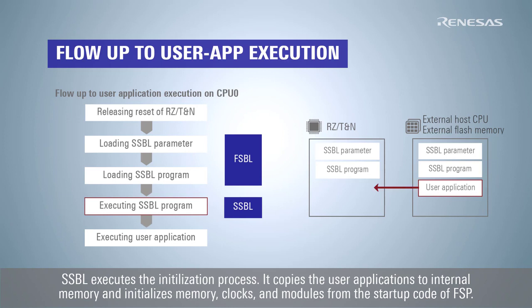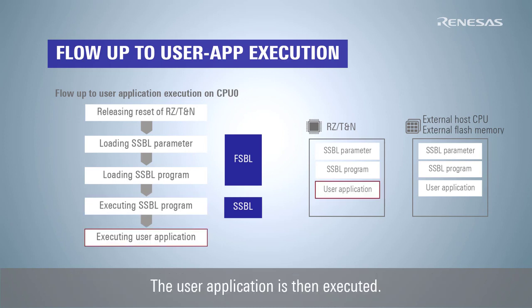SSBL executes the initialization process. It copies the user applications to internal memory and initializes memory, clocks, and modules from the startup code of FSP. The user application is then executed.